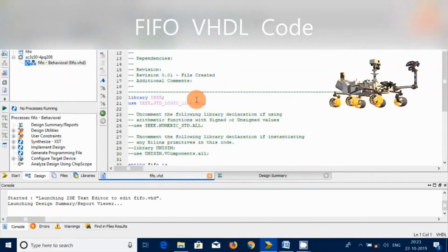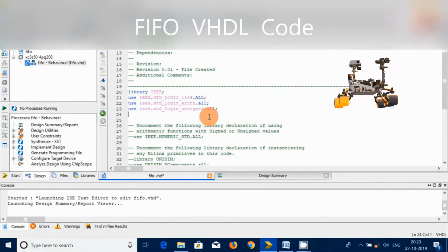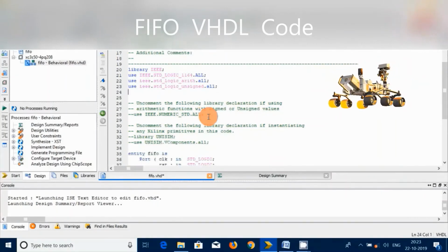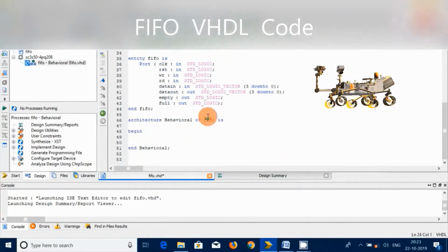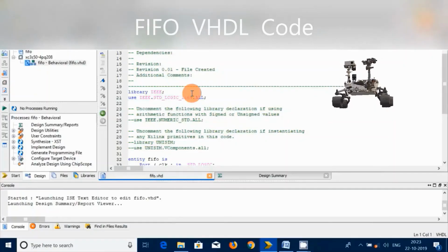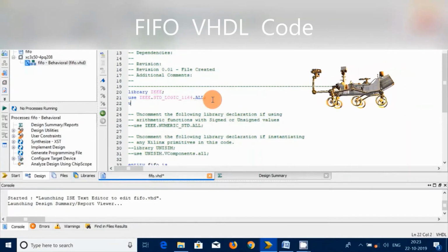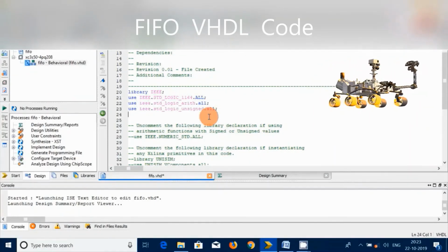In the standard FIFO, first in first out, when you write the first byte into the FIFO, nothing takes place on the data out bus until the read enable signal is pushed high for at least one clock cycle. Once the byte has been written to the FIFO, the empty flag will go low.